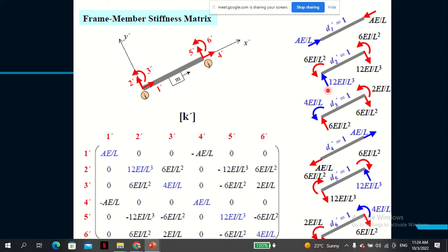Now the axial force only affects 1 degree of freedom. Moments and shear force affect 2 degrees of freedom. I think you need to remember that. So once you exhaust the first node, you go to, so this from 4, 5, 6 are dealing with the second node, and I believe I've tried to offer some good explanation.